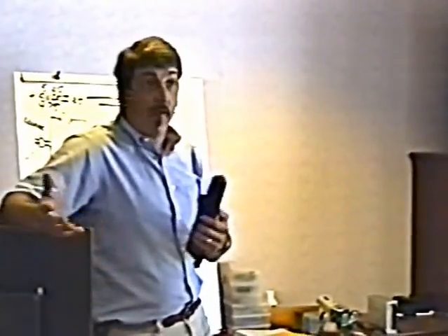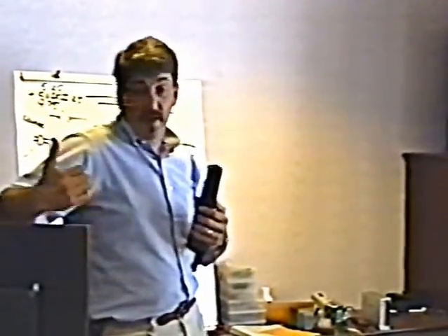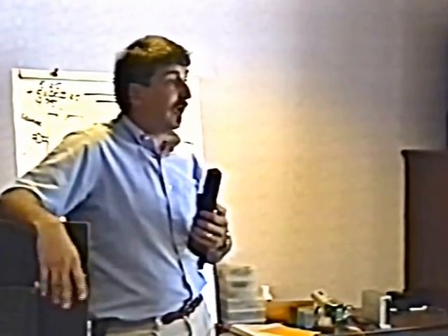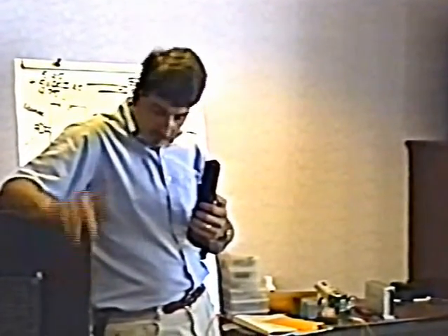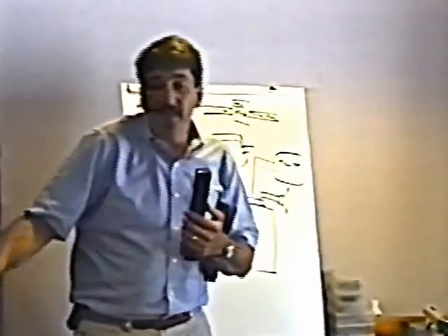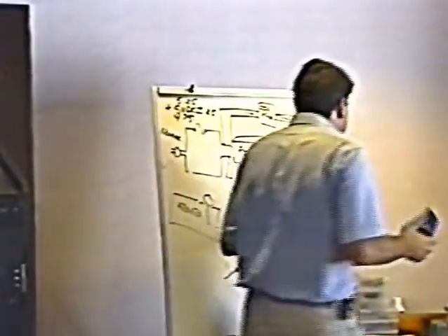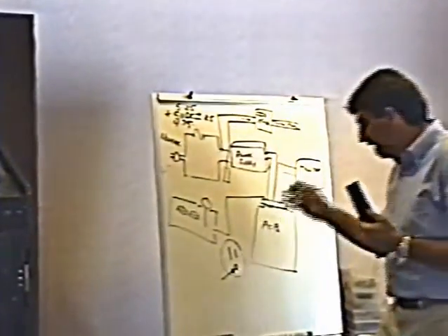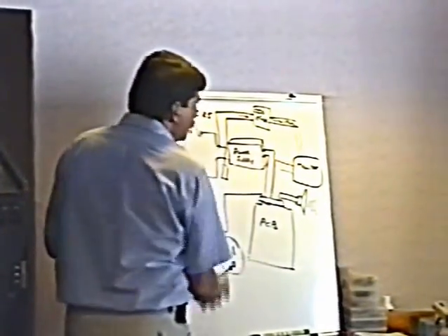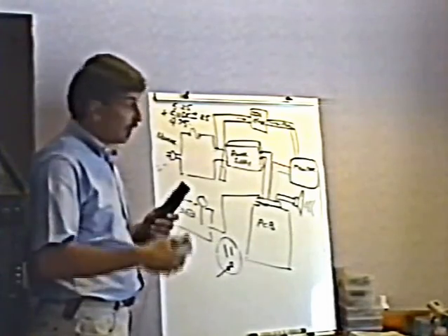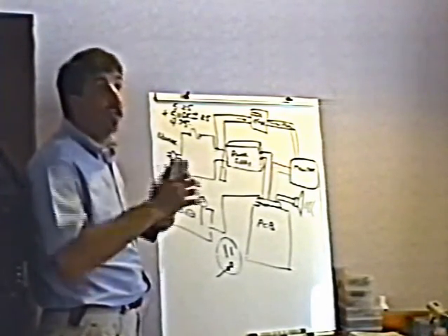Well, bullshit. Because it may work okay for a day or two, but you may be over-voltaging everything and blowing out chips eventually and so on. And speaking of chips, that's really the best place to check the 5-volt power supply. Checking it here on the JAMMA connector is really cool. If you have a JAMMA connector and you know that those pins are the pins, groovy.